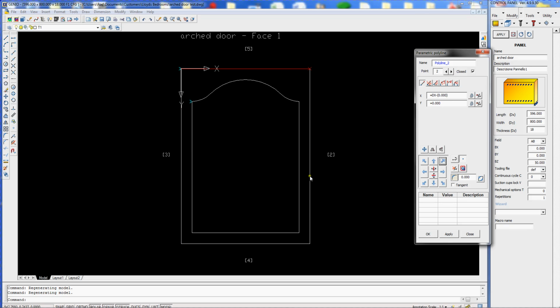If it is linked to the same all the way around, I can click on this icon here which says fixed distances to panel edges. If I click on that, that will automatically link all of the four corners in this case to that, so I don't need to click each corner. Click apply. If anything changes, then I know I've got something wrong. It's not, so click OK.